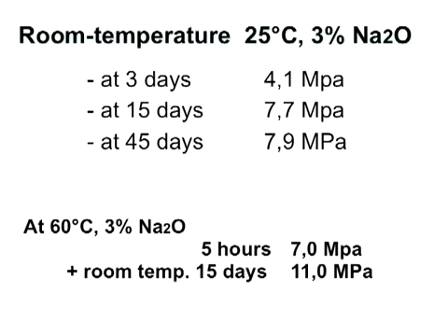Let's increase the temperature to 60 degrees C, which is practically nothing. After 5 hours, you get 7 MPa, and if you take the brick and let it rest for 15 days, you reach 11 MPa. 11 MPa, it is 110 kilograms per square centimeter.